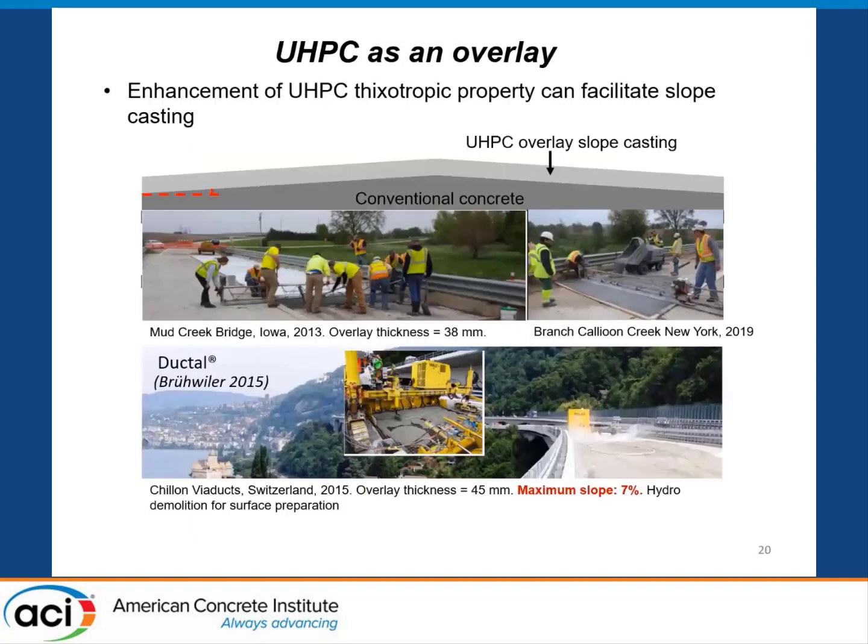Another application of UHPC rheology I want to talk about is the development of thixotropic UHPC as a thin overlay for the bridge deck. UHPC is normally developed with self-consolidating properties.